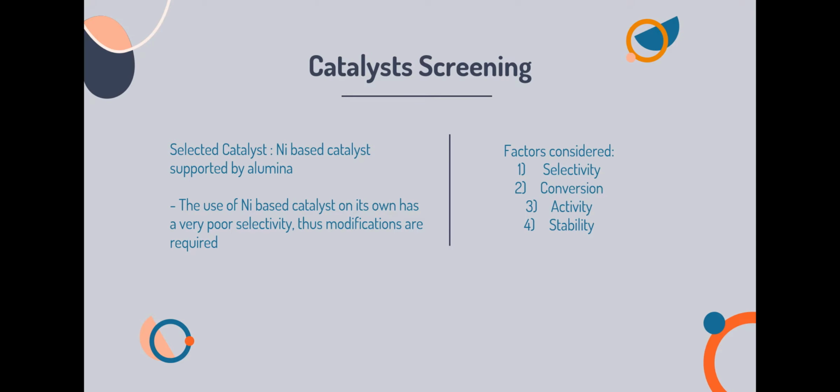For the catalyst screening, it is very important to consider several factors before selecting the desired catalyst. These factors may include selectivity, conversion, activity, and stability. The selected catalyst is the alumina-supported nickel catalyst, but the selectivity of these nickel-based catalysts is very poor. Thus, it is important to modify the catalyst to achieve better performance.